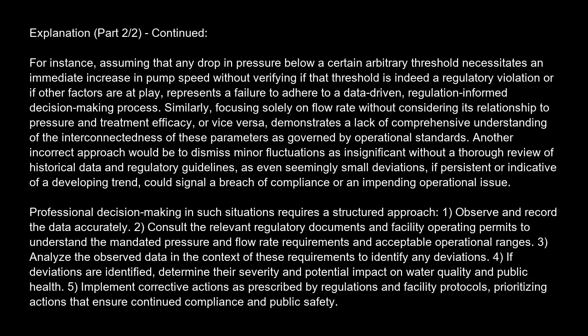Consult the relevant regulatory documents and facility operating permits to understand the mandated pressure and flow rate requirements and acceptable operational ranges. 3. Analyze the observed data in the context of these requirements to identify any deviations. 4. If deviations are identified, determine their severity and potential impact on water quality and public health. 5. Implement corrective actions as prescribed by regulations and facility protocols, prioritizing actions that ensure continued compliance and public safety.